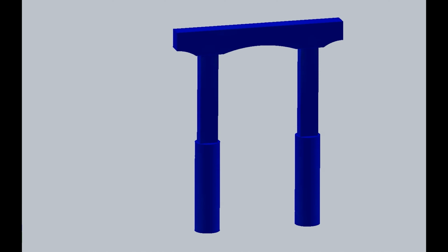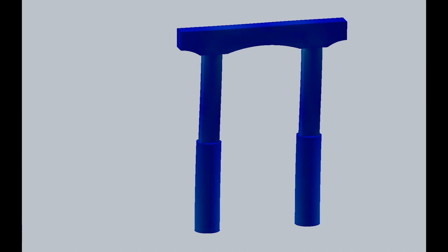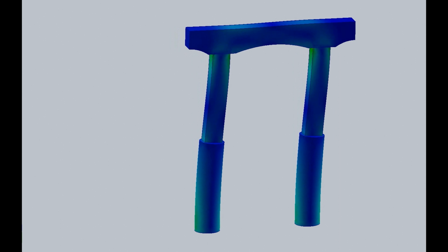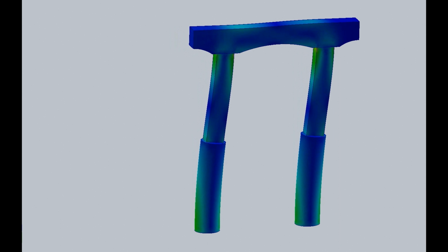Looking at a single bent, we can see the displacement demand along the local axis of the beam. To determine the displacement capacity, we perform a pushover analysis. Also known as a nonlinear static analysis, it predicts the hysteretic behavior of the structure under cyclical earthquake loading. We do this by modeling the structure and applying an increasing force. As individual members start to yield, other members pick up additional load and yield.